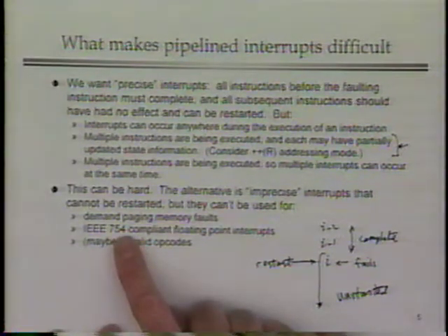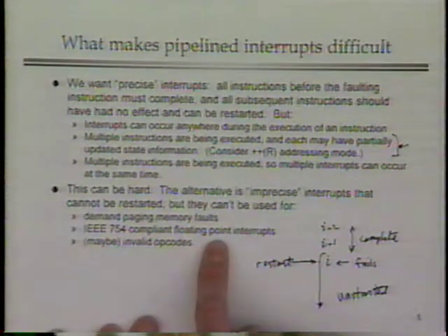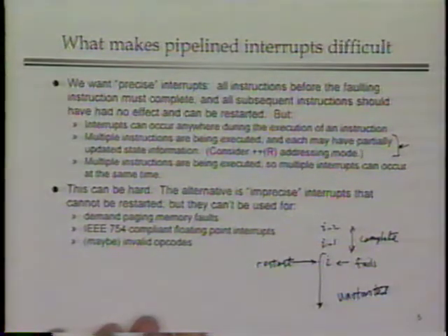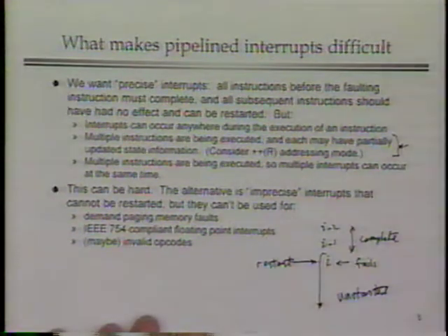The IEEE standard for floating point operation requires, if you're going to be compliant with it, that floating point interrupts are precise. They have interrupts for things like imprecise results, which require that you can record some information or fix something about the operands and then resume execution, continue the operation of the instruction string.